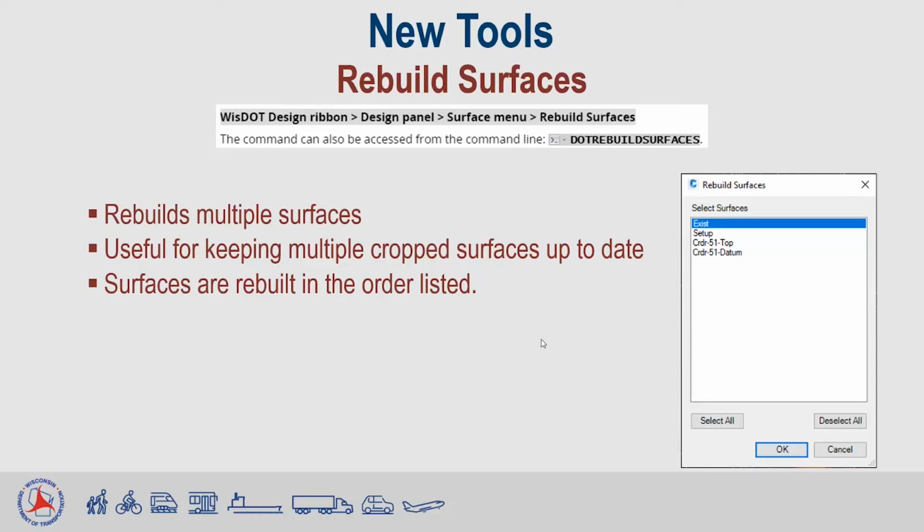One caveat here is if there are any dependencies from one surface to another, you have to keep in mind that this tool is only rebuilding surfaces in the order that they're listed in the dialog box here, which is usually just fine for using with the crop surfaces tool. But if you were going to use this rebuild surfaces tool for something else that has multiple dependencies and the order matters, then this tool might not be right in that situation.